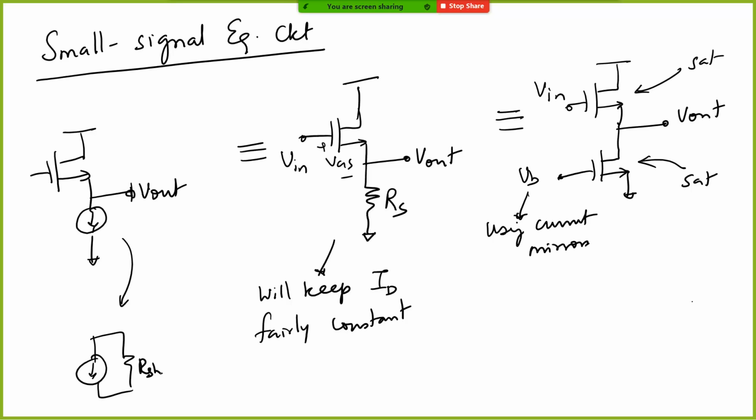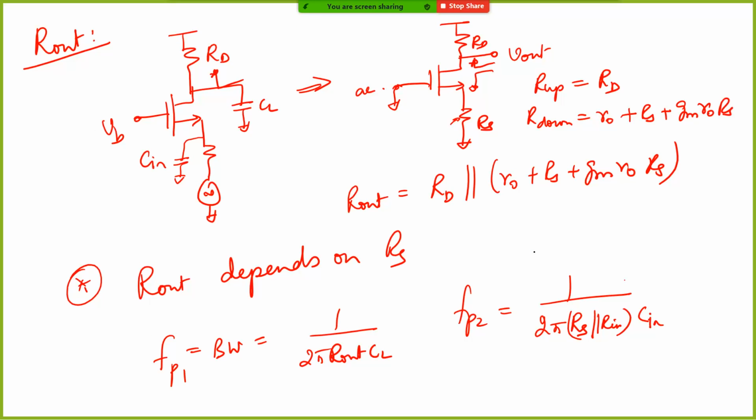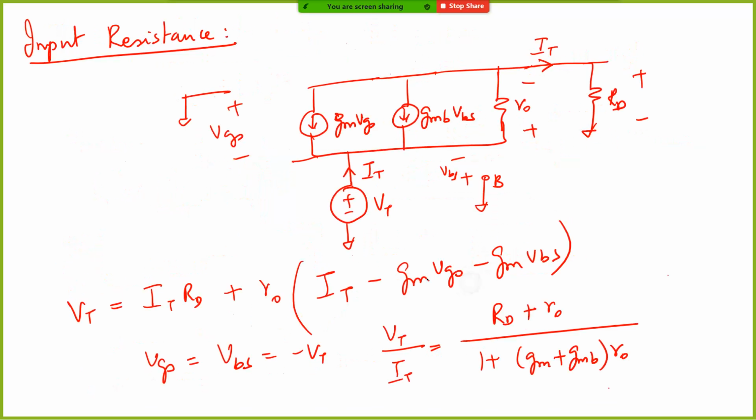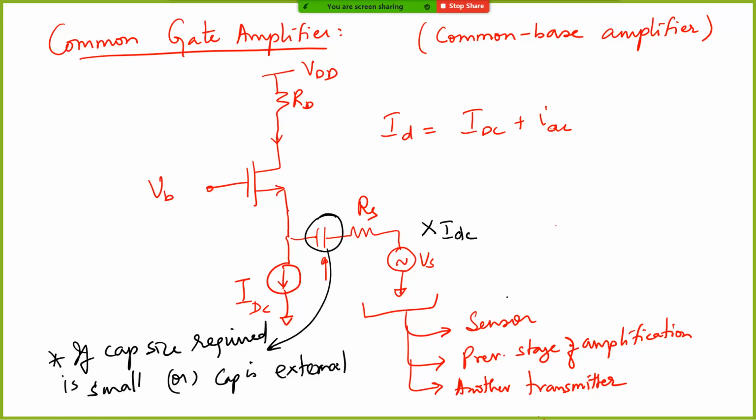All that you are doing is you have a current source. We did all this discussion saying current source, current source, current source. That can be implemented by using either a single transistor current mirror or a cascode current mirror. So the same thing goes for even the common drain amplifier, where we talked about a current source biasing it. Over here, I think I drew a current source.